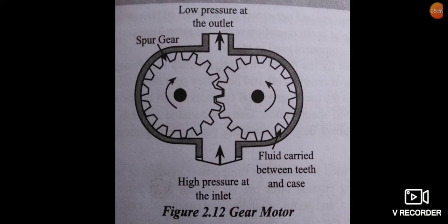Compressed air flows into the chambers formed by the housing and two successive vanes. Sliding vane motors will have 3 to 10 vanes. The air expands and causes the rotor to run. Air is exhausted as the leading vane passes the exhaust port. Speeds of 3000 to 8500 RPM are typical, and reversible units are available.